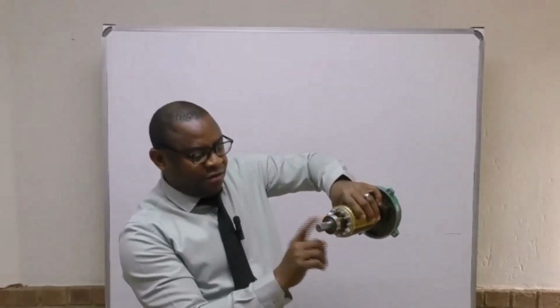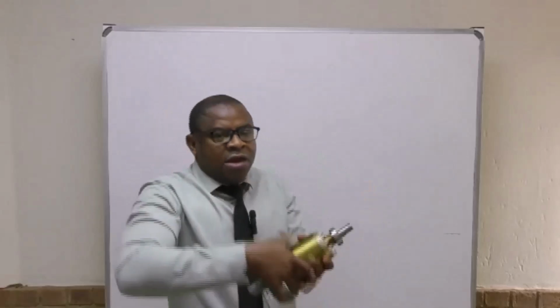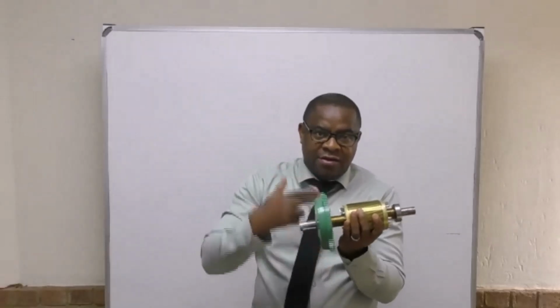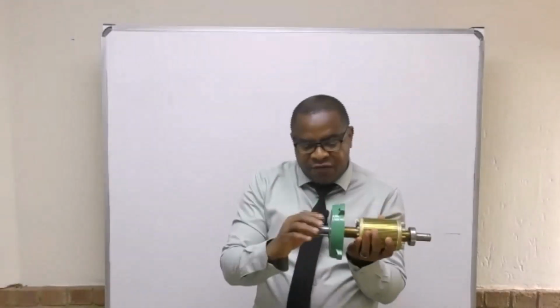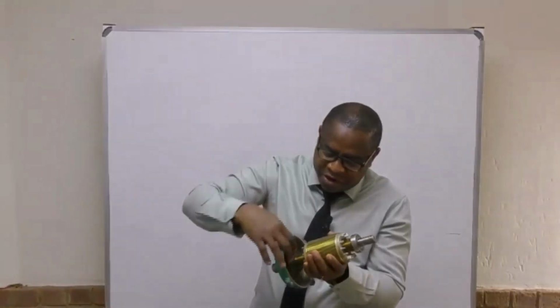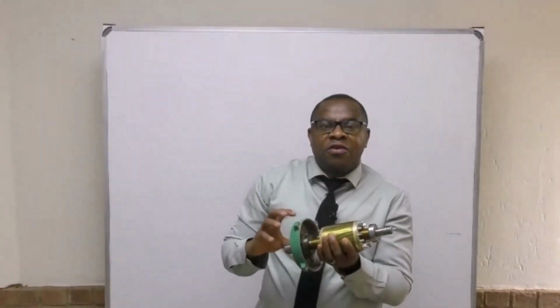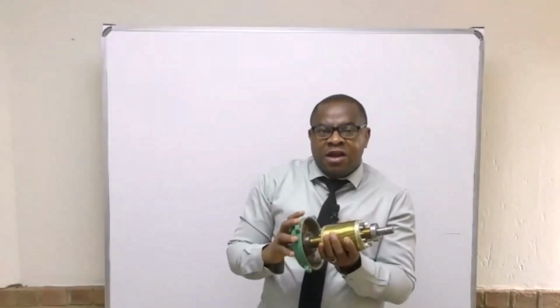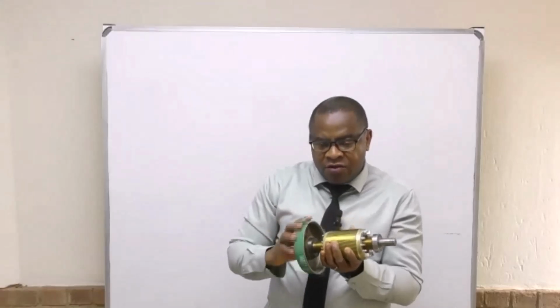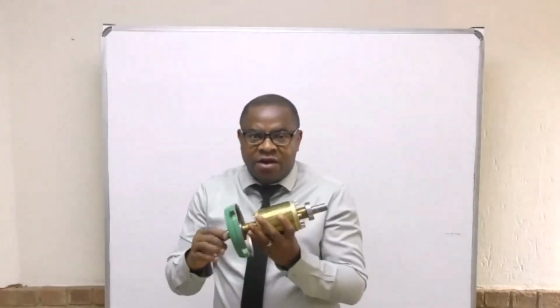On the shaft, if these bearings are not properly oiled or lubricated, then there will be some friction losses that will try to hinder it from rotating faster, so we need to really remove those losses.